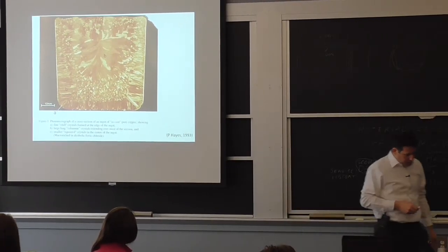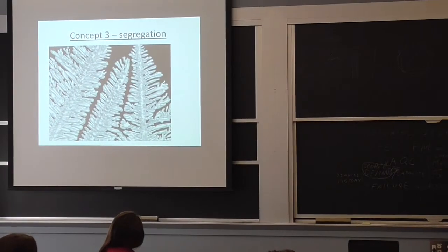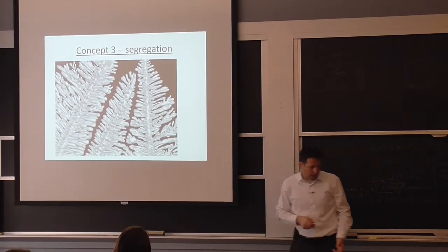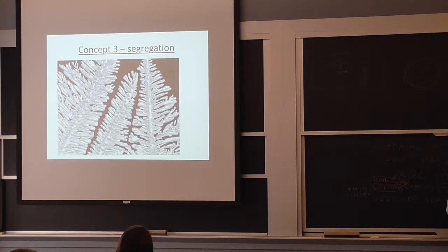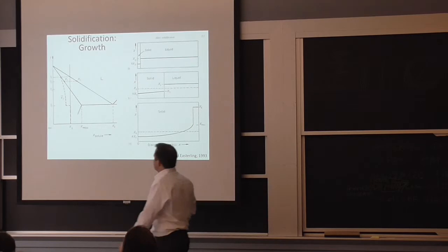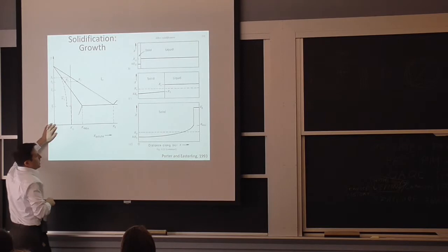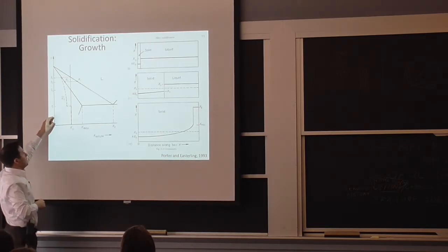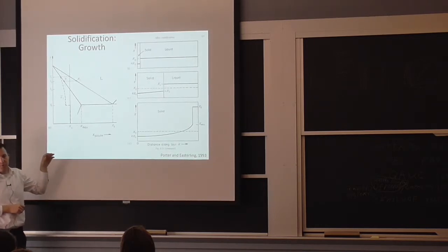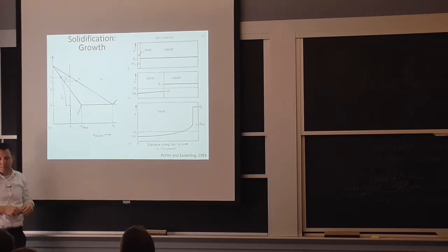The reason for the change in chemical concentration is that at first you produce more or less the pure metals. And that is based on the phase diagram. If I have just a regular alloy that has a certain melting point, what we're doing here on the phase diagram is we have temperature, and then we have the concentration of an alloying element. By adding an alloying element, most of the time you reduce the temperature of fusion. So it becomes easier to melt and it will cool to a lower temperature before it solidifies.